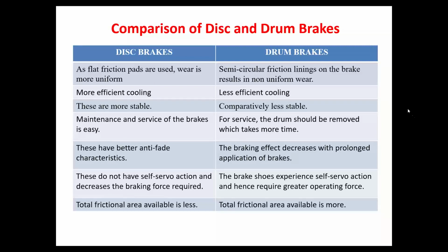One end of the brake pad wears out at a faster rate compared to the other end, so the life of the brake pad will be reduced. Instead of driving the vehicle for 10,000 kilometers with a good driving habit, you can drive it only for 5,000 kilometers, because one end becomes unevenly worn out, so that you can no more use it for braking purposes.